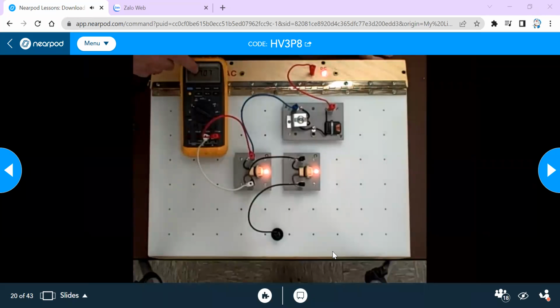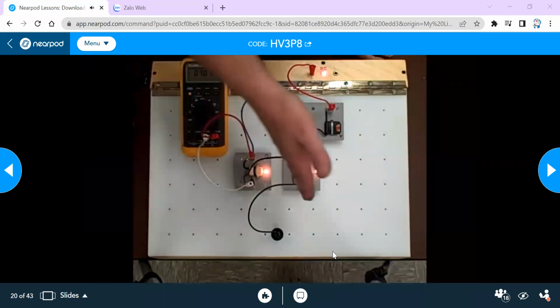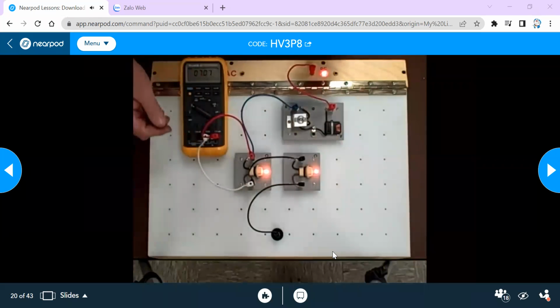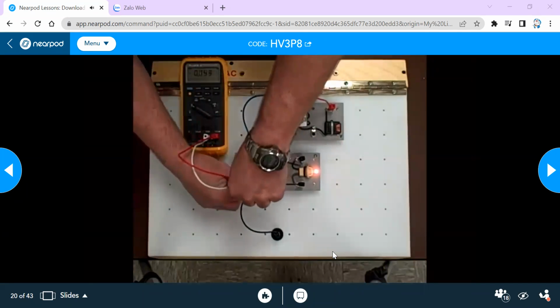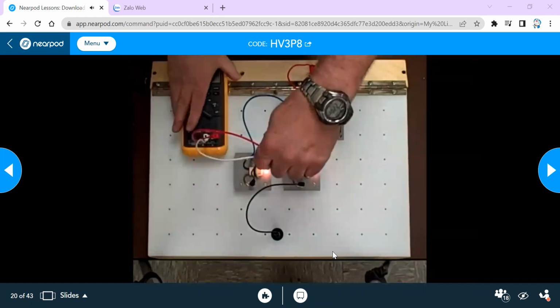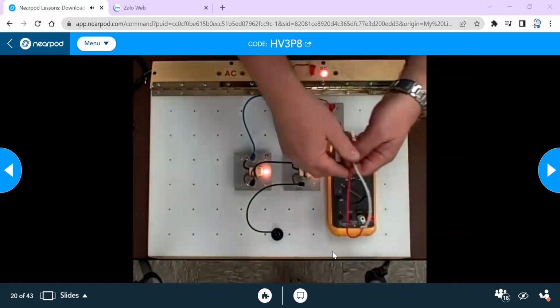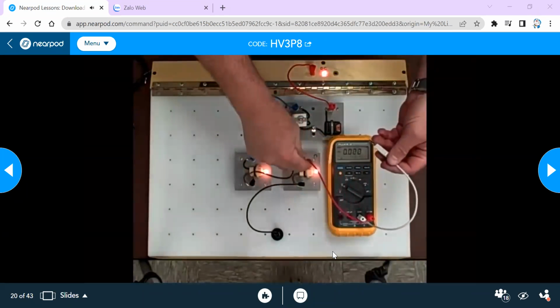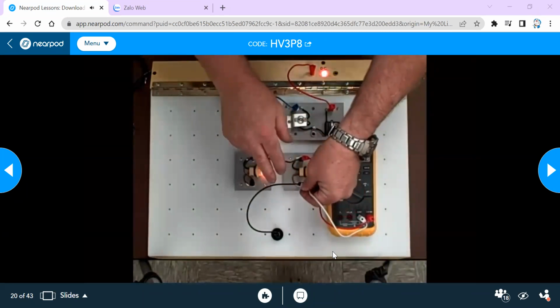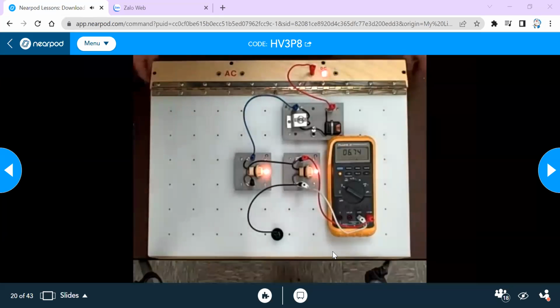Now we look up here, 7.07, so we round off to say 7 volts. There's a big V, no multipliers, so that is in fact 7 volts. Now, we'll also be dropping voltage over on this bulb. So let's move over there. We'll just move the meter over here, and we'll go upstream and downstream, and we find 6.75 roughly, or 6 3/4.